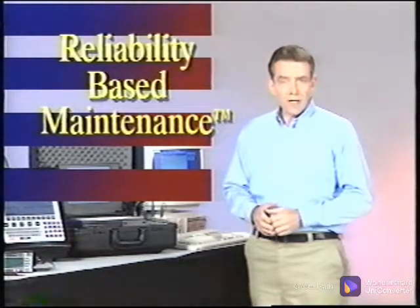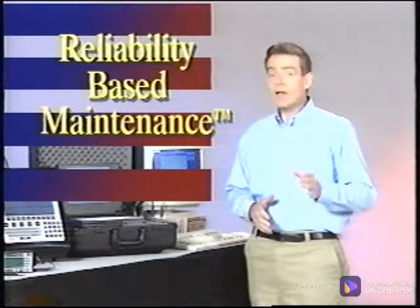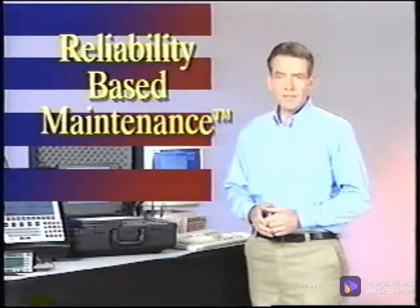Here at CSI, we are seriously committed to the success of your reliability-based maintenance programs using predictive and other proactive maintenance methods. When diagnosing problems, spectral data gives a lot of information, but sometimes key elements are missing from the spectral data. Instead, these key elements are often found in waveform data. For this reason, it is extremely important for you, the analyst, to be able to use the waveform data to confirm or pinpoint the source of any problems.